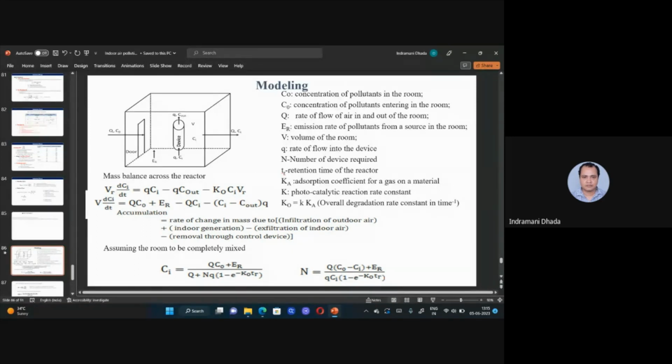So you have to change the concentration at the source. At the source, you have to go for scrubbing technology, because it is a gas. In scrubbing, you are using lime water to arrest SOx, spraying the lime water. Now you have to design your scrubbing system to control this additional 20 ppm, because 40 ppm is safe, but 60 ppm is not safe. So your limit is 40, and you are releasing 60. That means 20 ppm you have to control. For this 20 ppm, you have to design your system. You can control this SO2 to the 40 ppm level and release that. This is one kind of thing.